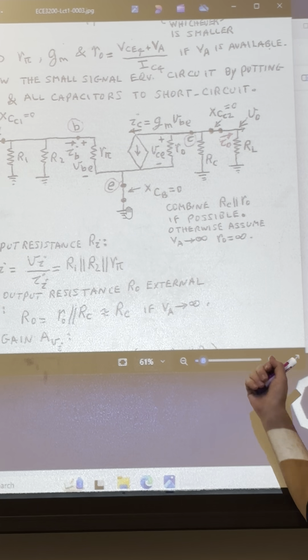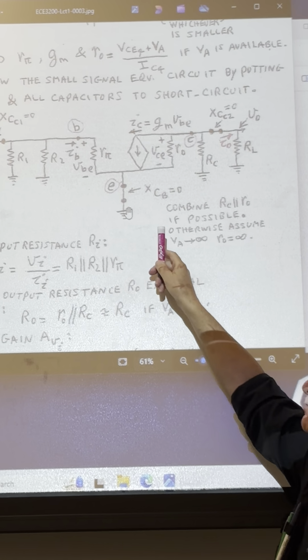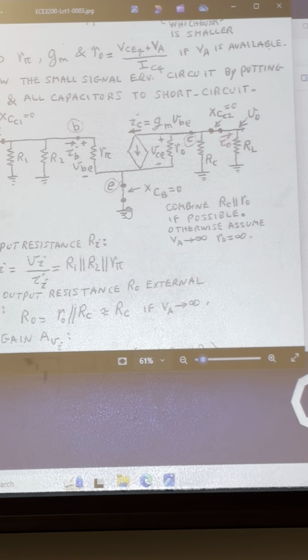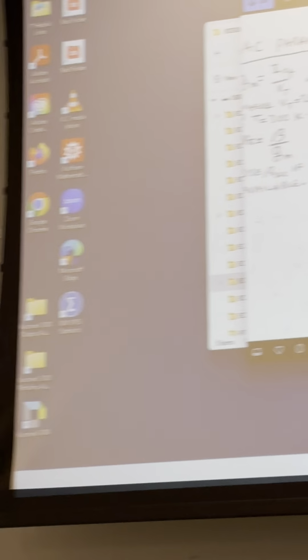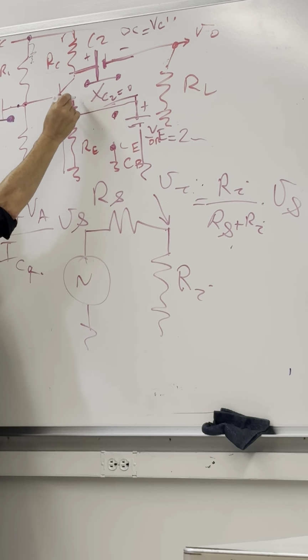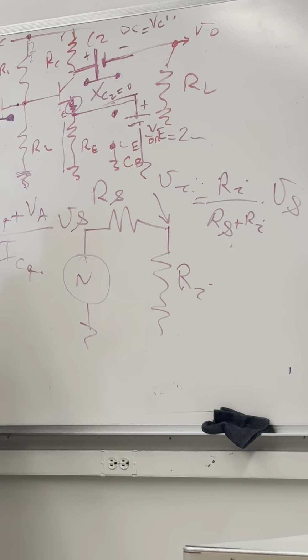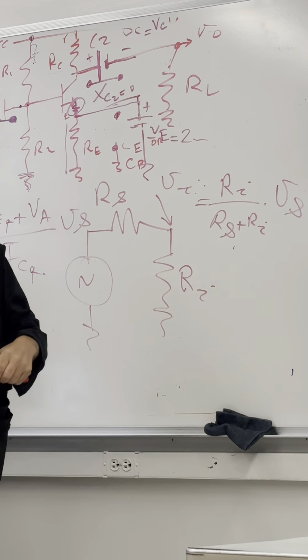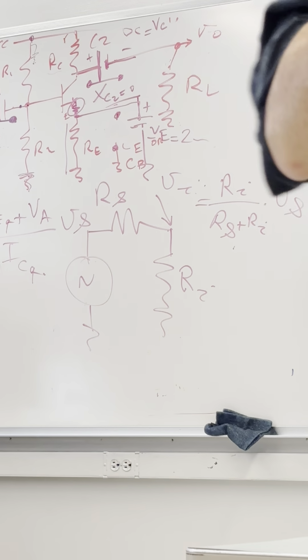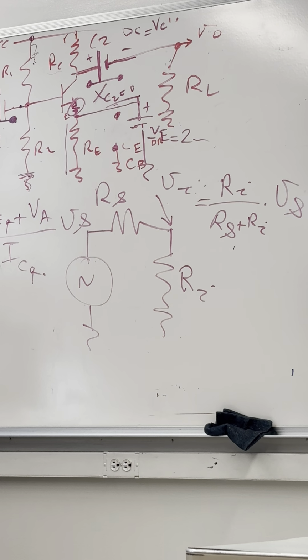We take the capacitor out, not completely, but partially. In other words, look at this trick. We put the resistor there, and then put the capacitor here. So we short circuit this part, but still we leave a little tiny resistance over there, what you put in series with the emitter. It gives you great advantages, but also the negative side of that is to lose the gain. You lose the gain. But the circuit becomes completely independent of beta. It gives you a good linear gain.